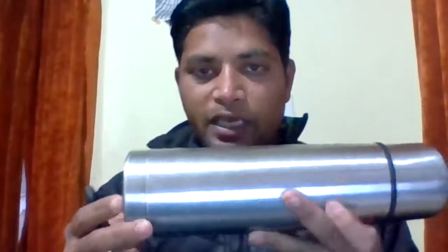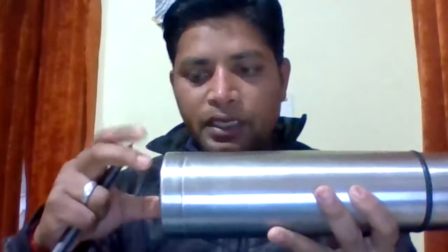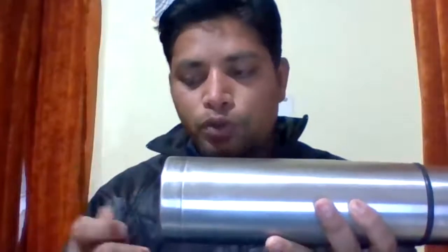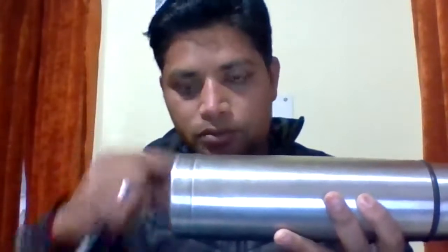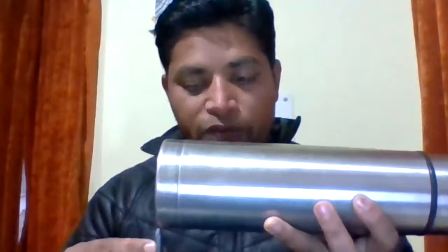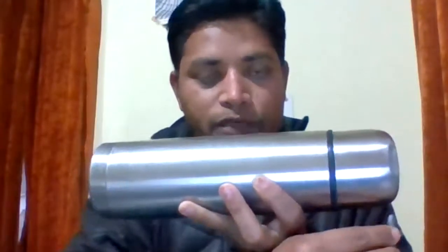But again, if this is 10 mm and you have to reduce the diameter to 8 mm, what we have to do is, if we are providing a depth of cut of 0.5 mm, then a total of 1 mm of material will be removed, because it removes throughout. If we compare these two, 0.5 mm from this side and 0.5 mm from this side, so it will remove the 1 mm material. So with a depth of cut of 0.5 mm, we move from here to here, and it removes 1 mm of material throughout the diameter.